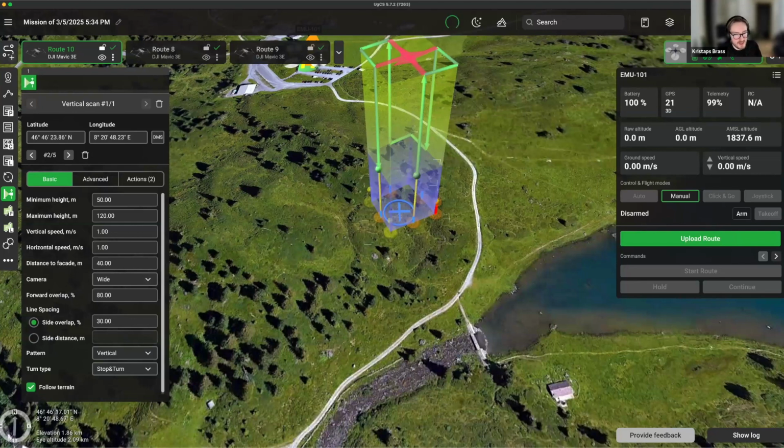And I've heard from IMU manufacturers that whatever calibration you do, as long as the sensor gets woken up and gets shaken, it's fine. It will do the job. There will not be a very significant difference whether you do a figure-8 calibration or a back and forth calibration. More or less all of them do the same thing. You can probably also use the figure-8 to calibrate, even if the sensor manufacturer says you have to use this specific other shape. So of course, take everything I say with a grain of salt, but at least that's what I know, and what I've been told by the people who make those systems.